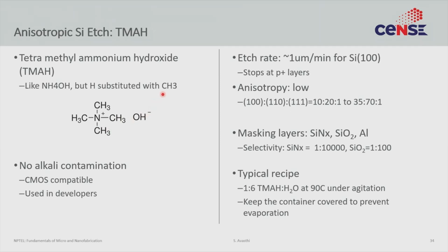and then we have tetramethylammonium hydroxide. This is actually a very strong base, and this does the same job that KOH does chemically speaking. It provides OH minuses which actually do the etching. The advantage is there is no alkali, there is no sodium, there is no potassium, so this is CMOS compatible. In fact, developers that are metal ion free, which are compatible with CMOS processing, actually use TMAH as a base, not potassium hydroxide.